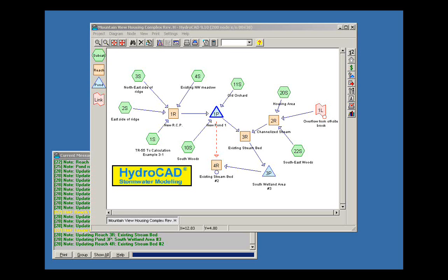Basically, the curve number lag method is intended for areas where you don't have detailed enough information to determine exact flow regimes. It generally is not mixed with other procedures. So if you had an area that was coming down to a stream and you wanted to model that stream separately, perhaps as a reach, then you should probably end your TC calculation at the point you come into the stream. Usually they're not mixed together.